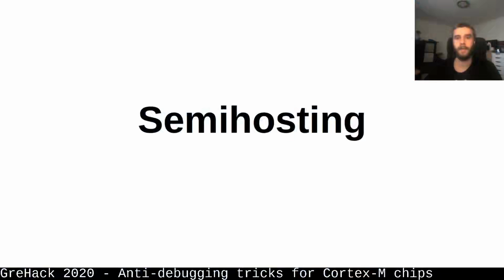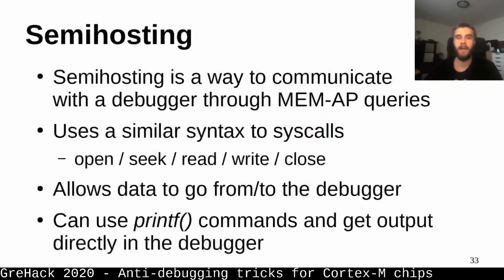If you read the ADI documentation, you might stumble upon the semi-hosting features. Semi-hosting is a way for the debugged application or device to query or to put data on the debugger computer. This is quite useful. For instance, the device can write log files directly on the debugger computer. It can also read test data from the debugger computer to the device, or it can simply be used as a printf equivalent, but directly from the SWD.